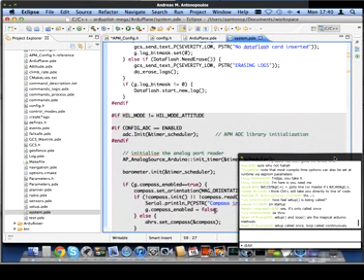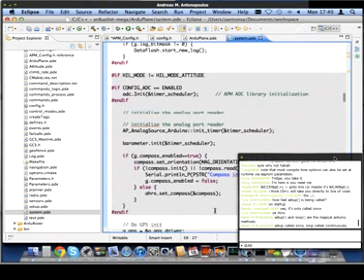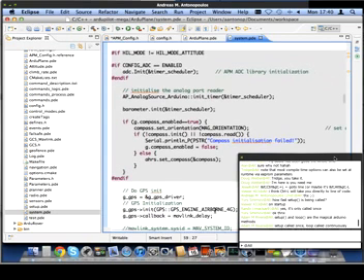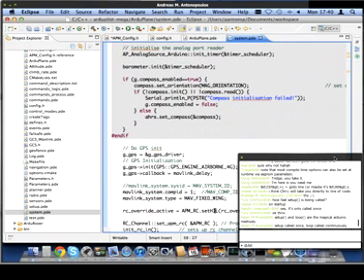We set those up. We also set up things like the data flash, which is the little bit of 2 megabytes of flash memory on the APM1, 4 megabytes on the APM2. We configure the analog to digital converters. That's what that adc.init does. The APM1 has a special SPI bus enabled analog to digital converter that has 8 channels, and we use those channels for reading the gyroscopes and the accelerometers, and also one channel is used for a temperature, and one channel is used for the airspeed.